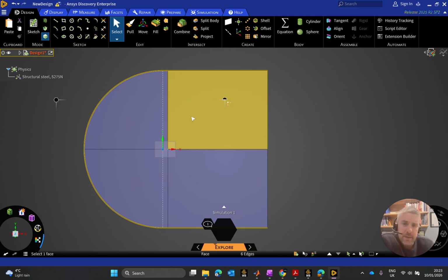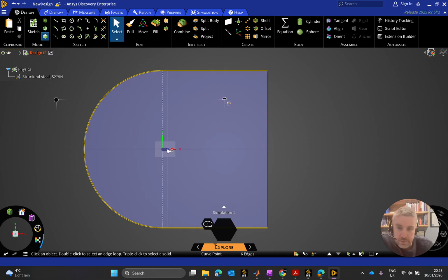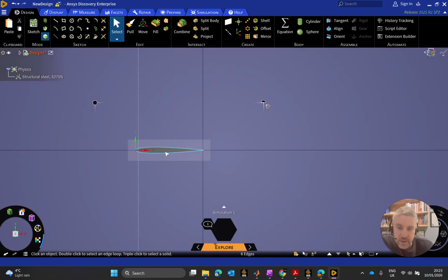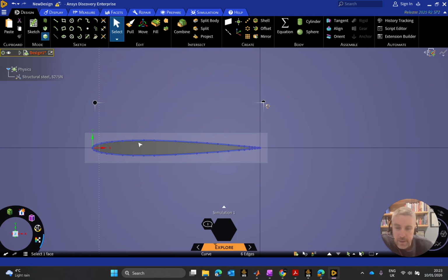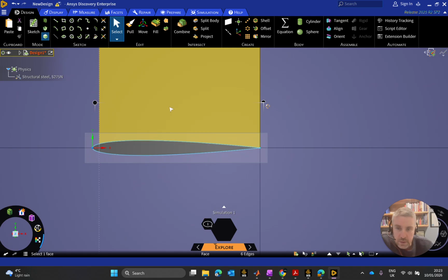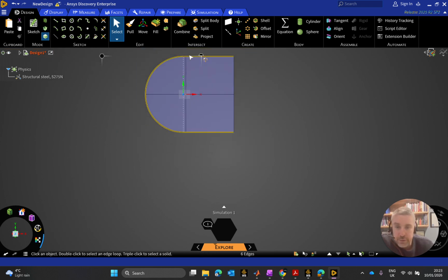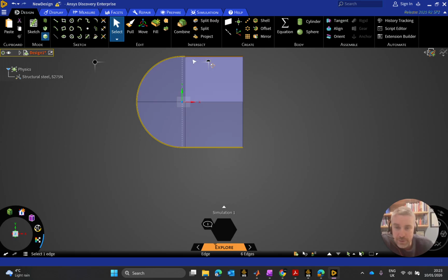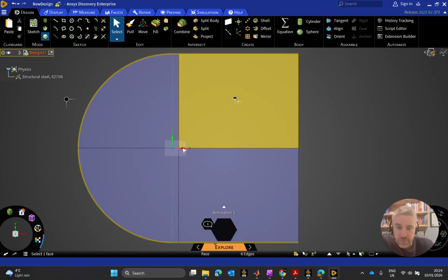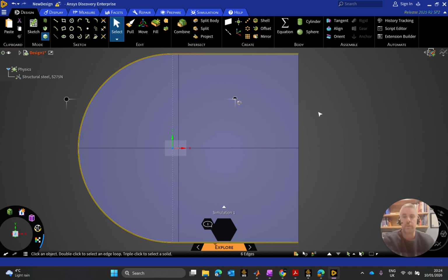But it might not be accurate to what's happening. So if you can imagine in a 2D world, if that is the front of your wing, your front wing, apologies, and this is above the front wing, and that is on a table that is 1.2 meters off the ground, and your ceiling is 3 meters high, that's the closest boundary above your car is going to be the ceiling. So it's a vast distance up. So if we're only going up that height, which might be at your head height really, if you're looking down on your car, there is no boundary there. It's just air.